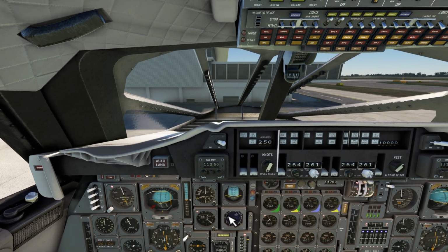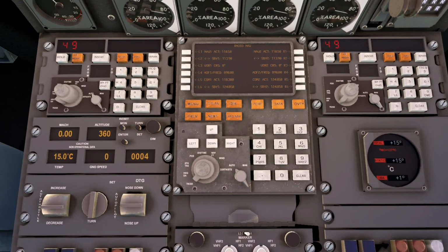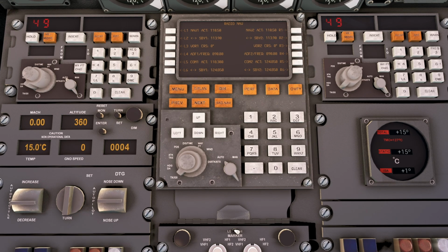And finally, our QNH is set correctly. It's a bit difficult to see, but the airport altitude is correct. Next up, FMC. In our very archaic flight management computer, we have to program GPS position, reference airport, gate. In the flight plan, we have to choose our departure runway 26 right with no SID.